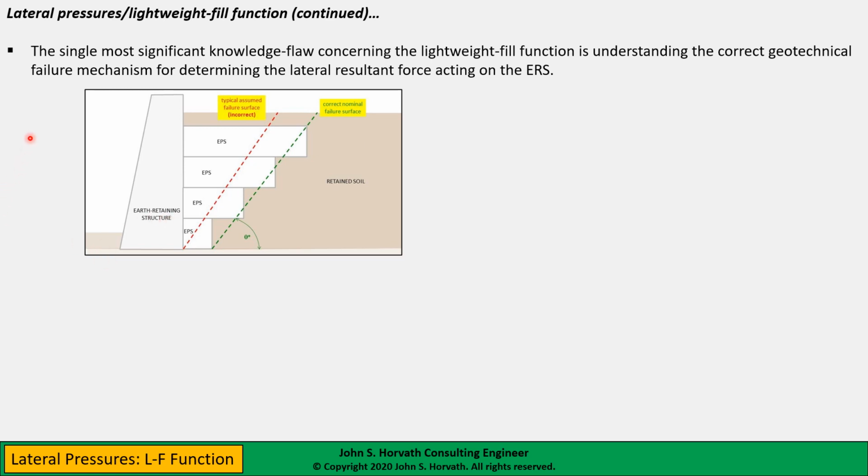Coulomb, on the other hand, a century earlier in the 18th century, explicitly assumed the existence of an earth retaining structure, and that is part of his boundary condition. So the only solution would be the Coulomb solution, or if you prefer, one of the more modern 20th century enhancements, such as the Kötter and Caquot-Kérisel.